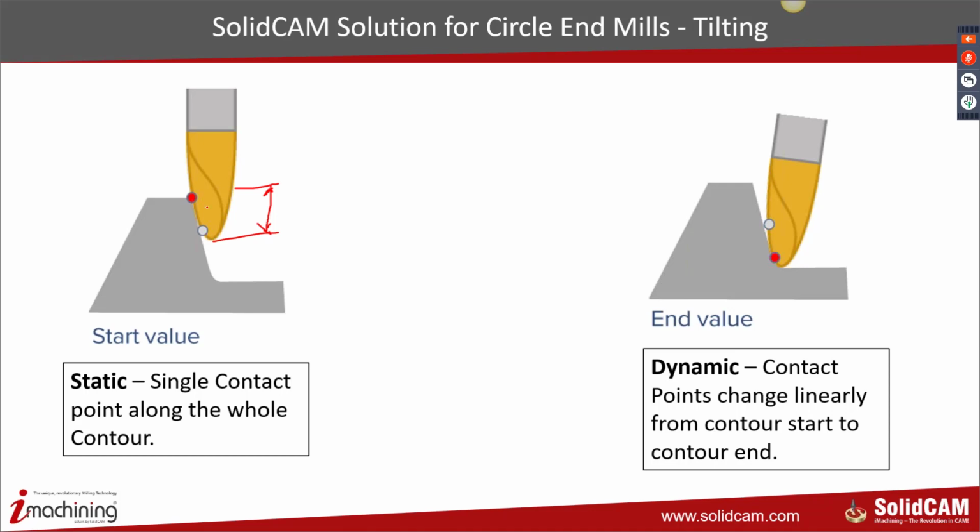Another way is to say I don't want the distance of the tip, but I would like a certain percentage over the barrel profile. So I can say maintain the contact point at 30% of profile. Again, it will determine what is the contact point, and it will keep tilting the tool in order to maintain that contact point always on.